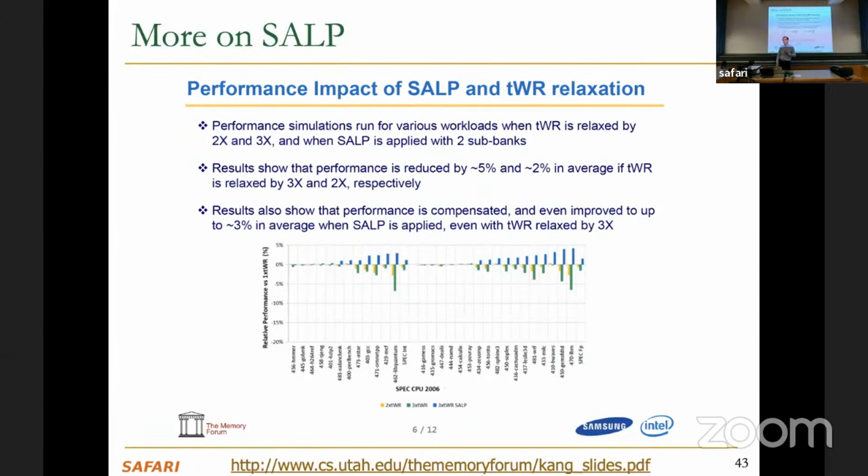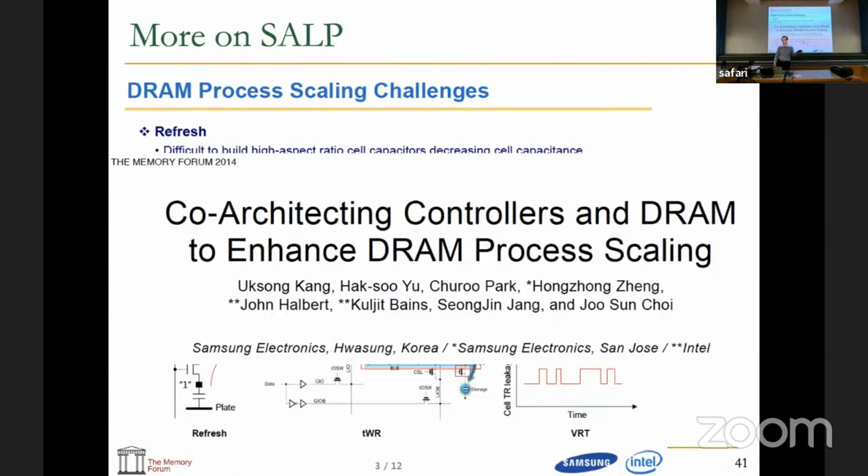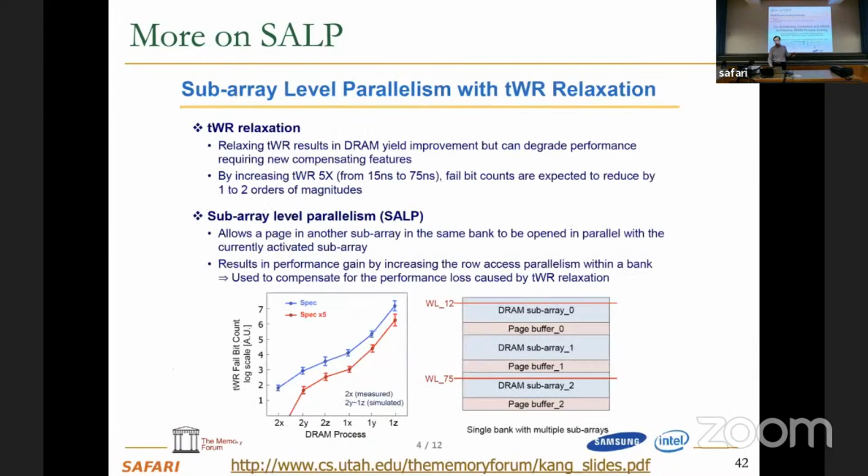Okay, so the main difficulty, well, certainly you need changes to the DRAM. This also requires changes to the memory controller. Basically, this requires changes everywhere, meaning memory controller and DRAM. In the memory controller, you need to keep track of which subarrays are active, right? And you need to add new commands. You need to change the interface to switch between subarrays. So it requires a lot of changes. And essentially, it's all doable. It's not that difficult, in my opinion. I don't believe that these are very difficult changes, but people are very resistant to change in general.